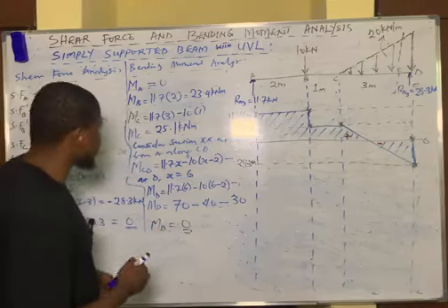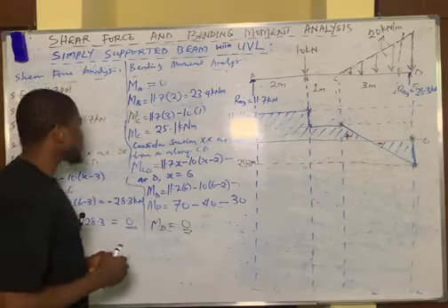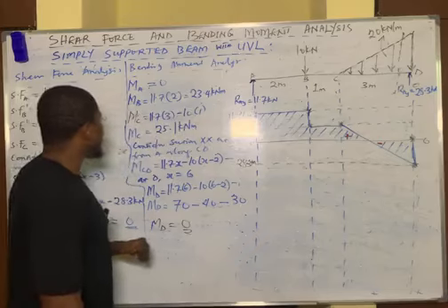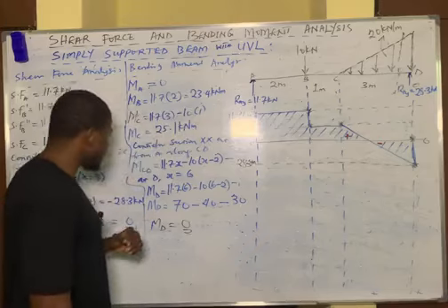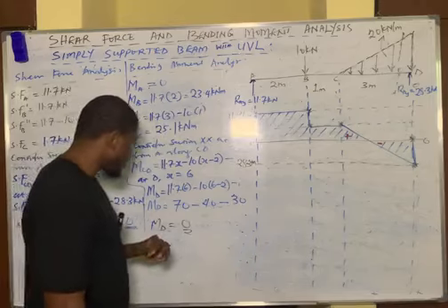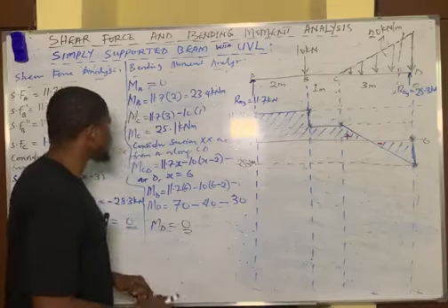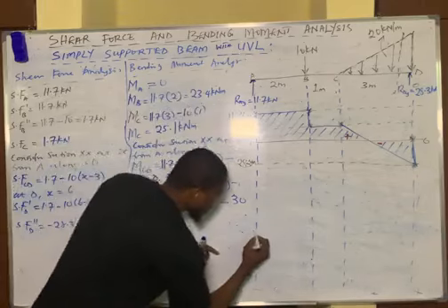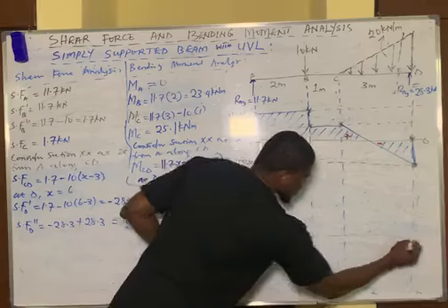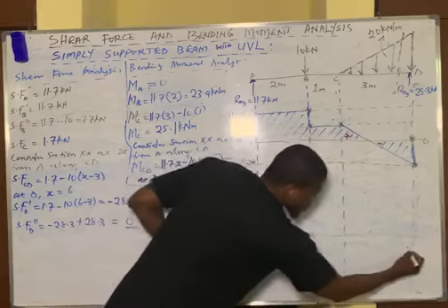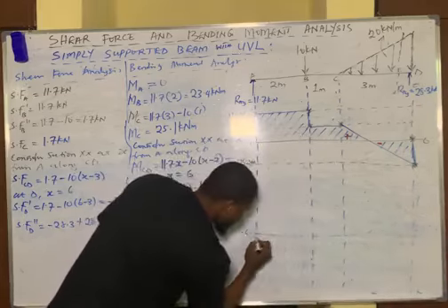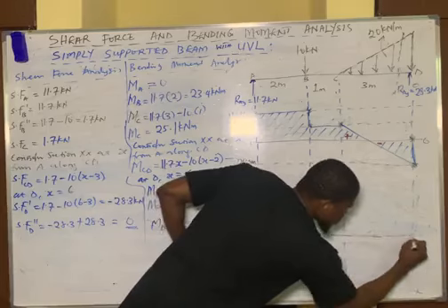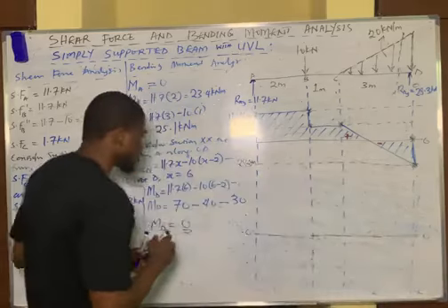So just like we did in the shear force diagram, let's pick out the highest number from the lowest, right? So moment at B, 23.4. We have 25, seem to be the highest for now. 25, any other value, 0. So 25 is the highest, followed by 23.4, and then 0. So we can simply call here our baseline. That's our origin, 0, 0.